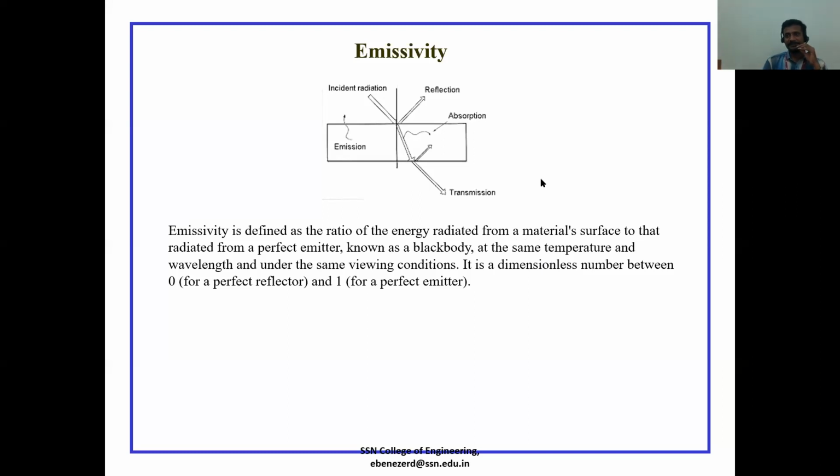Yes, ma'am, so the total amount of energy that we calculate for emissivity will be reflection plus transmission, isn't it? No, that is entirely different. What you see here, reflection, absorption, transmission, is entirely different from what I'm talking about, which is emission. Emissivity is the amount of energy that is coming out of a surface because of its temperature. It is not what it is reflecting.